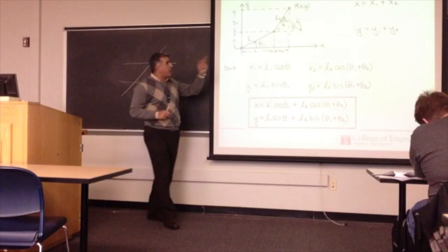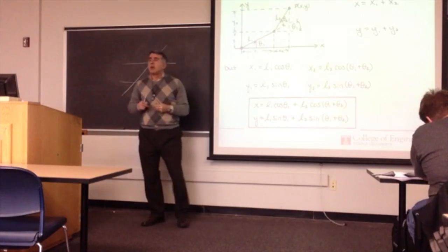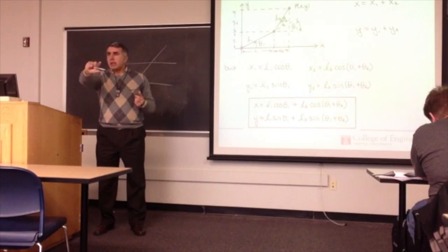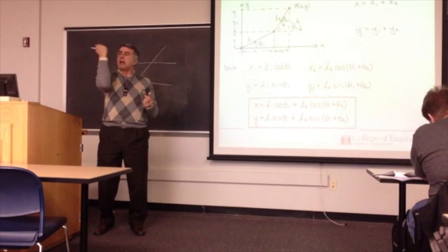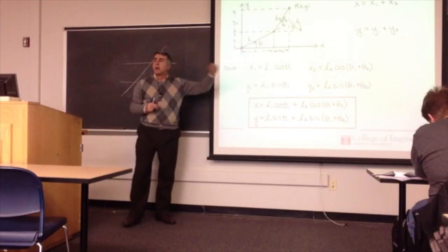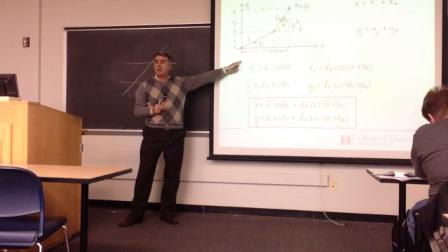You have to think about it that the rotation of these arms is done by a motor. And the motors basically revolve. They don't move things linearly. They rotate, and therefore the angle goes up and down. So what you have control on that motor is the theta. That's why we have L1 and theta 1.